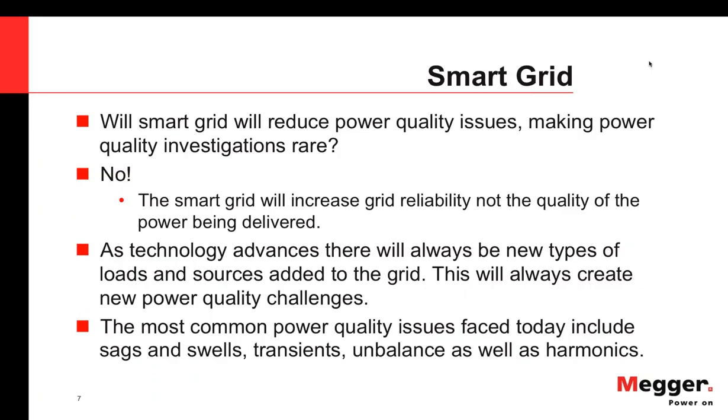And one of the things that I've been asked is, will smart grid reduce power quality issues? And the simple answer is no. The smart grid is meant to increase grid reliability, not the quality of the power being delivered. In fact, as these technologies advance, there will always be new types of loads and sources that get added to the grid. And this will create new power quality challenges that we're going to see.